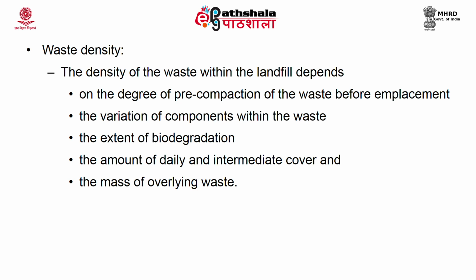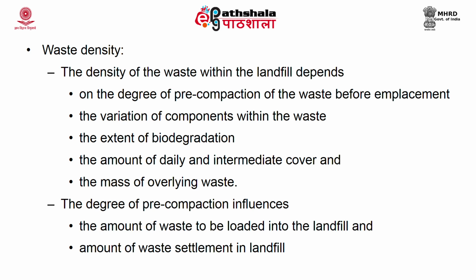Then the density also varies or is affected during the movement of the trucks or lorries which carry the waste. The lorries are heavy-tired vehicles, and when they carry the waste they will be very heavy, and when they go across these waste cells, obviously they will compact the waste and the volume gets reduced. So, the degree of pre-compaction of the waste influences the amount of waste to be loaded into the landfill. It will also influence the amount of waste settlement in a landfill.